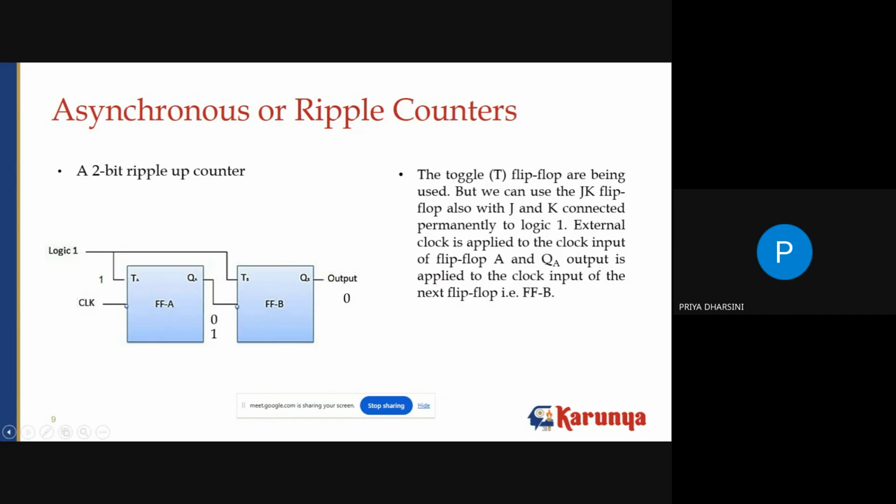So now, is it a negative or a positive trigger? The data here is shifted from 0 to 1. So now we are undergoing what kind of a shift? Are you all able to realize? 0 to 1. So it is undergoing a positive trigger. The clock pulse is moving from logic 0 to logic 1, high. So it is a positive trigger.